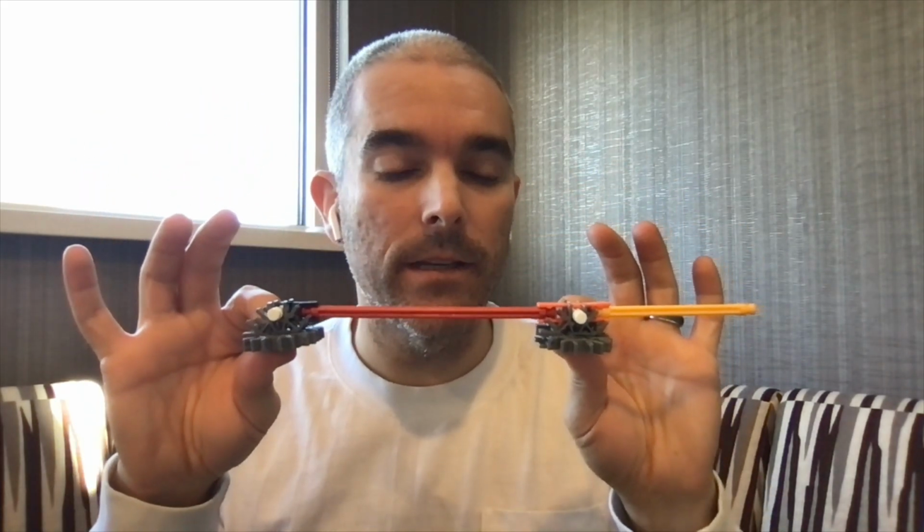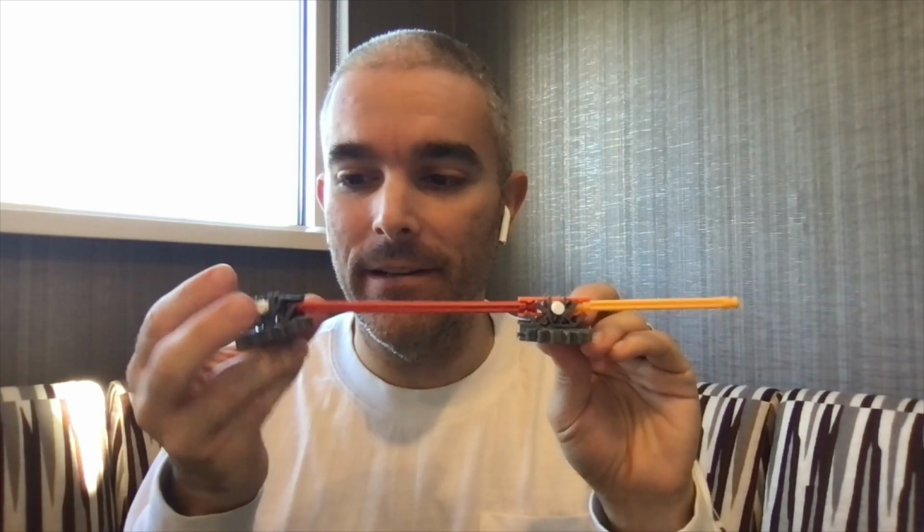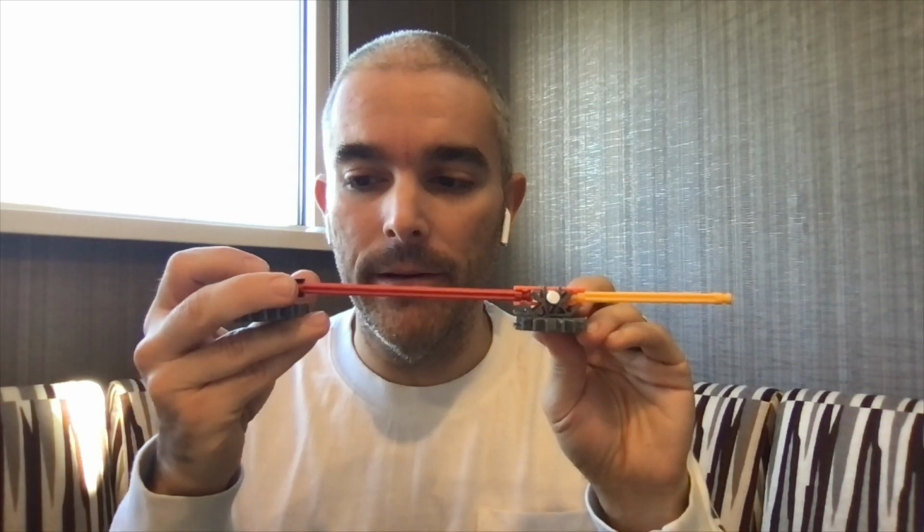Here I have a little model of this particular bridge, so I'm going to try to draw this. This is point A, point B. For the influence line at A, we need to remove the support reaction. So I'm going to remove this and apply a unit displacement. I'm going to move this up a value of 1.